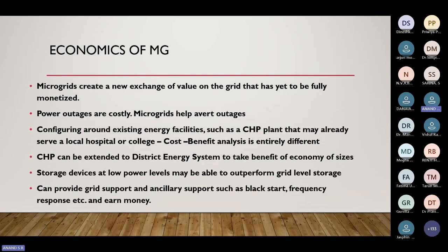And again, in the case of offices, government offices or private sector offices, the consumption will be mainly during the daytime only. During the evening hours there will be little consumption, but by evening hours the commercial consumption picks up. So that kind of distribution, that kind of diversity in demand, if it is there, it can be utilized.